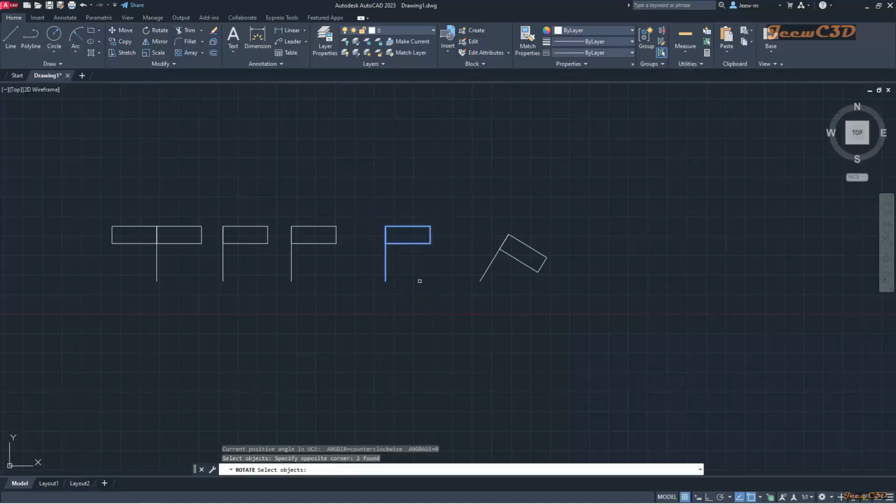Select the object and right click. This time I will rotate from here. So if I rotate, it will automatically rotate from that object. You can see, you can even give an angle here, but since we haven't used the angle options yet, I am not going to give an angle. Instead, we will just use the mouse cursor location to get the rotation angle. Let us say I will stop somewhere here. So that is about some of the basic AutoCAD commands, and they are always used widely.